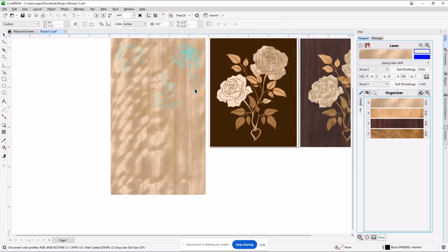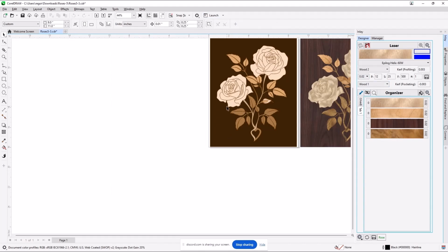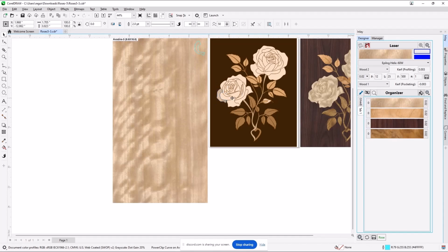We've got pieces here. What Vincent's program does correctly that I didn't do is, remember, I got all these things in here and I'm positioning them around. The correct way to do it if you're actually going to paint with veneer is to not do every piece in one fell swoop. You select this one, you hit the veneer. You select this one, you hit the veneer.